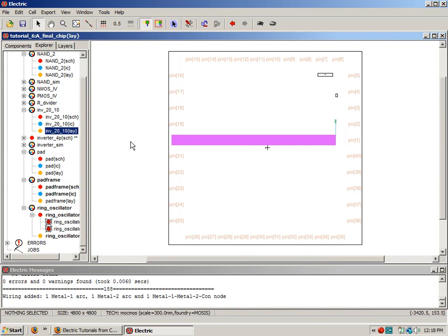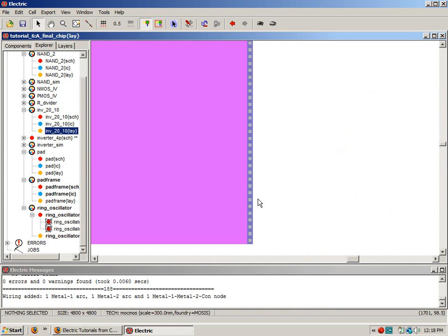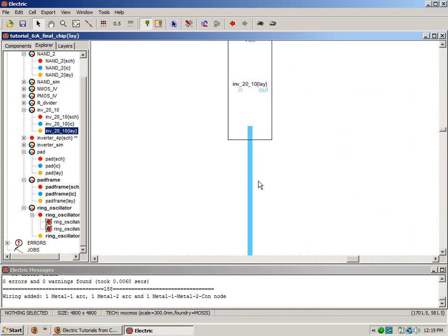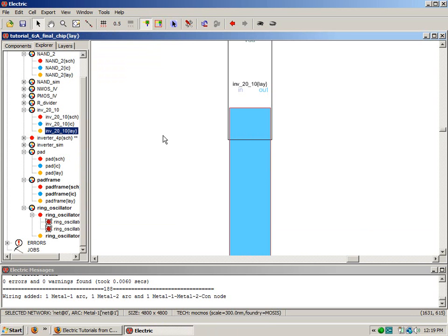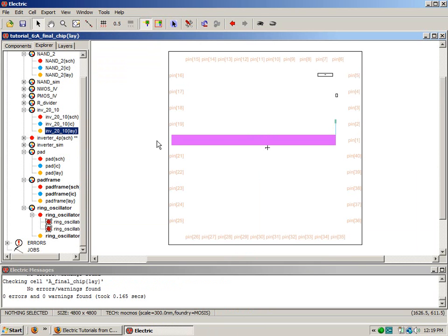And if I do that, I get this long piece of metal 2 coming over to metal 1 and going up. And there's the vias going up to connect ground. And again, I'm not going to size the conductors. That would be something you'd do: Control-I and then go to 30 or whatever and change things. All right, I'm not going to do that. Okay, so we can hit DRC, no errors. Before I go any further, I'm going to export that.